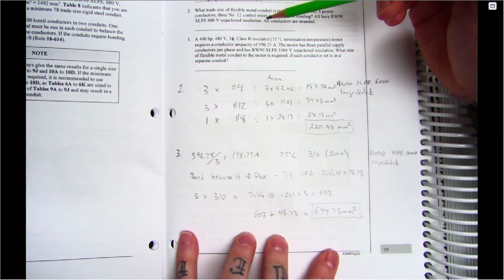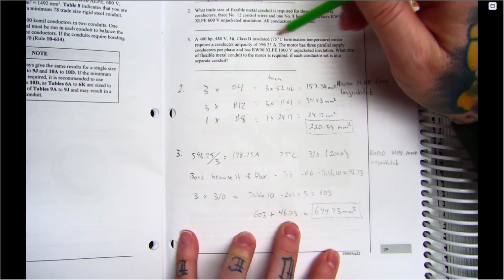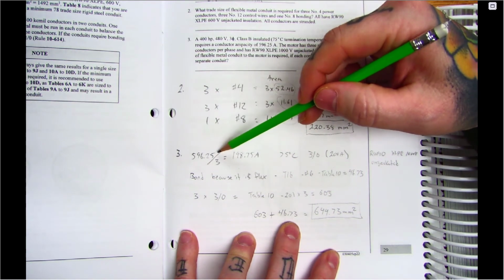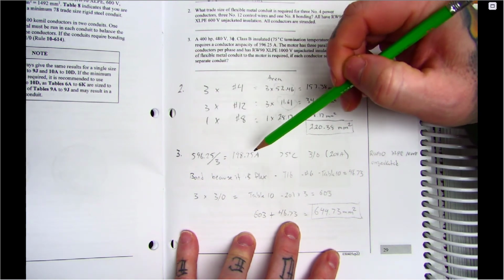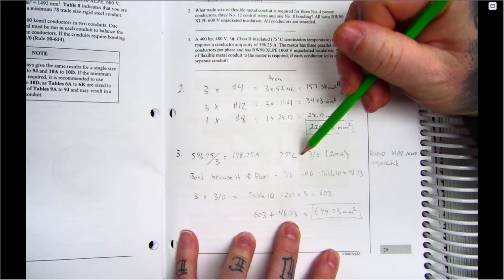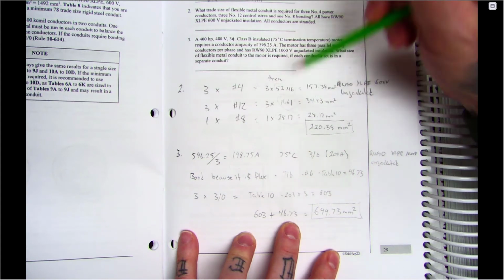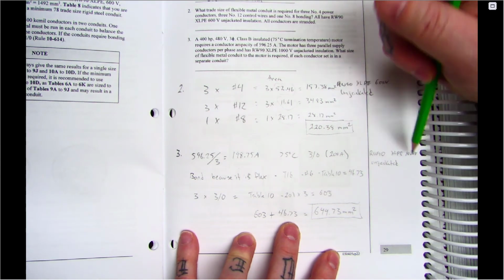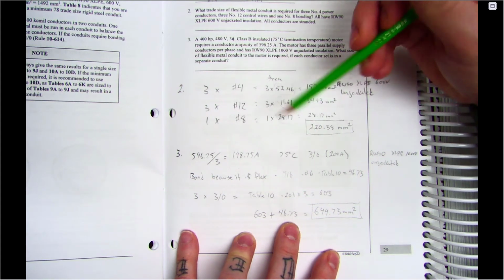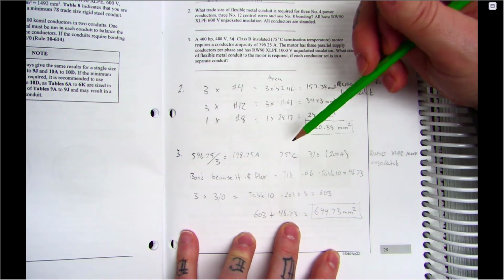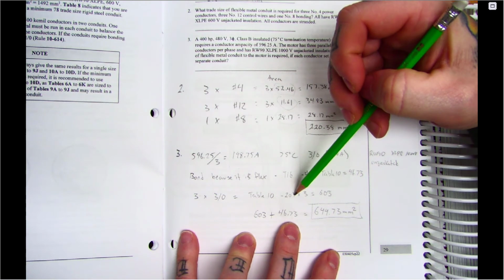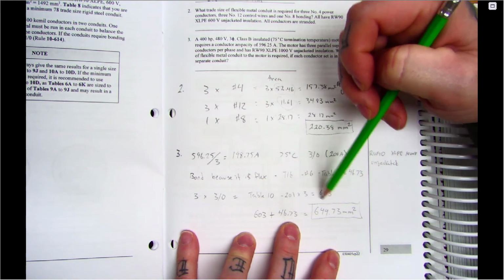Question 3, the thing we've got to watch out for here is they're saying that we're splitting this into 3 parallel runs. So I took that original ampacity, divided by 3 to get this new parallel run ampacity, and sized my conductor from Table 2 in the 75 degree column, because that's what it said up here. So I see I need 3 runs of 3/0 that are good for 200 amps. That gave me the type of conductor I needed. So I know now I'm just sizing it per conductor, even though there's going to be 3 runs, they're all going to be the same. So I get 3 3/0. I go to Table 10, get 201 as the millimeter squared, times that by 3, I get 603.